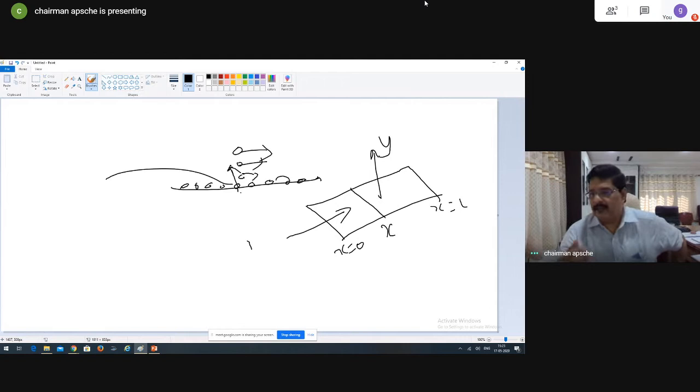The fluid patterns continue to change as they move along the plate, and therefore the convection heat transfer coefficients will be different at different locations. You will appreciate it as we discuss the laminar and turbulent concepts of the boundary layer. If I come to know the convection heat transfer happening between the solid and the fluid at a distance x, and calculate by that equation, I call it h_x.